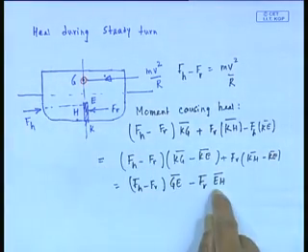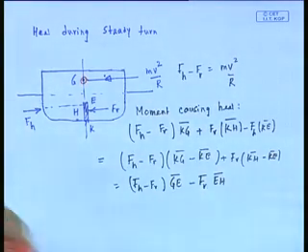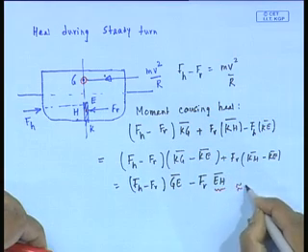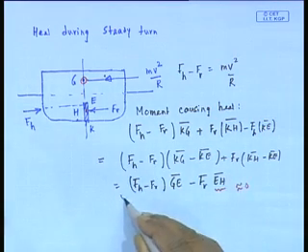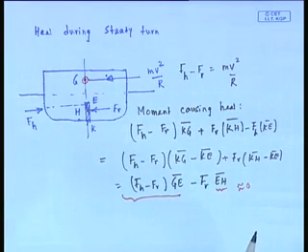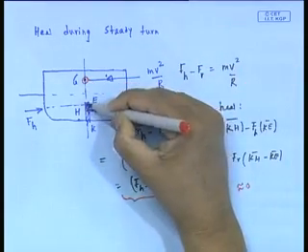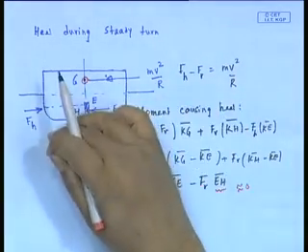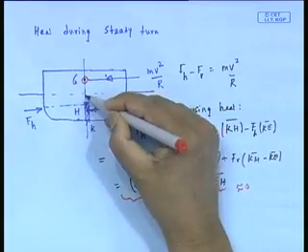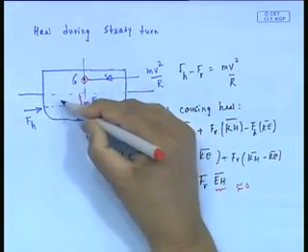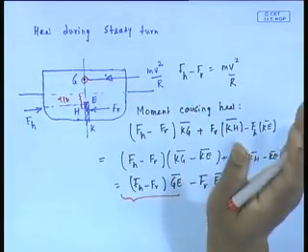So essentially EH can be approximately close to 0, so that my heeling moment turns out to be essentially this, where GE is G to E, and E can be taken as the middle of the draft, T by 2 if T is the draft.